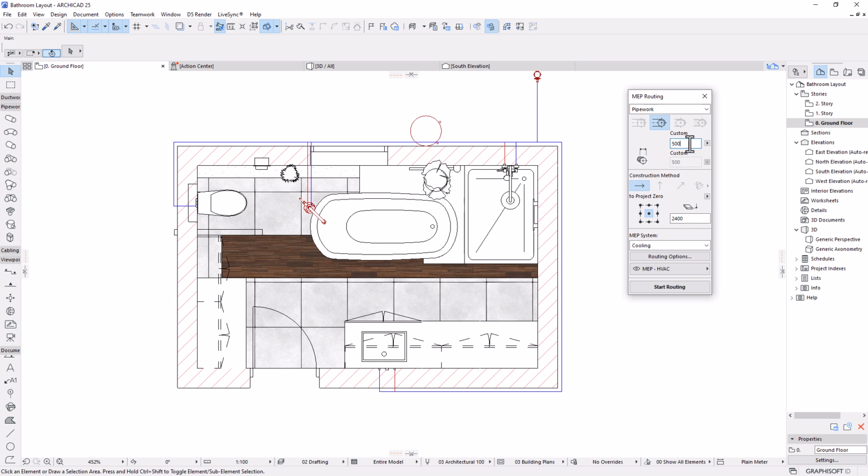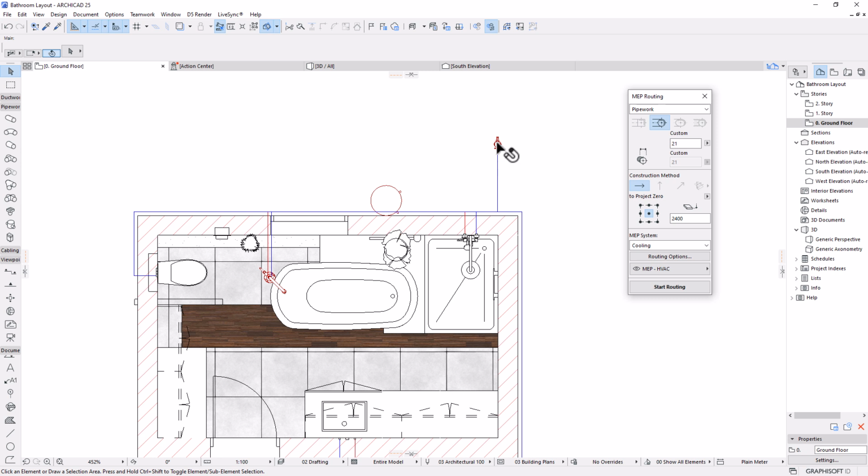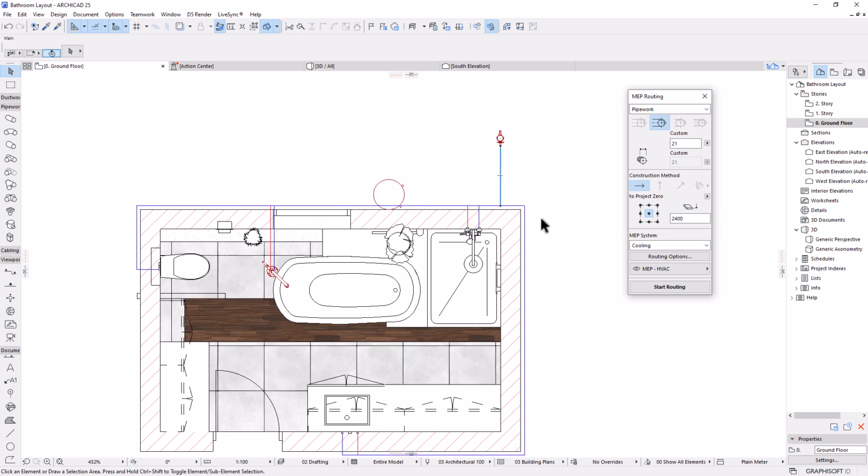We need to set the dimension or the diameter of our piping. Obviously the main supply is going to be a different diameter than what's in the house, so normally that's how the situation is. So I'm going to start around 21, which is from before the meter to the meter. Once it takes off from the meter, the size is going to change, and we're going to use a tool called the transitional size or transitional tool to achieve that.